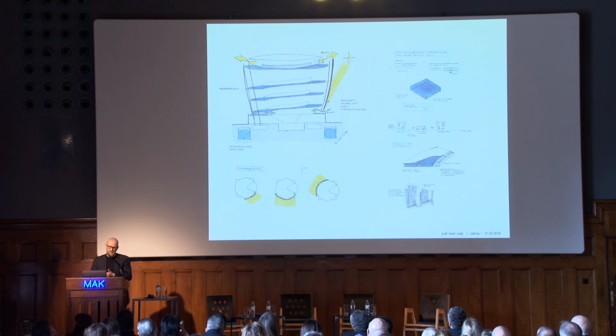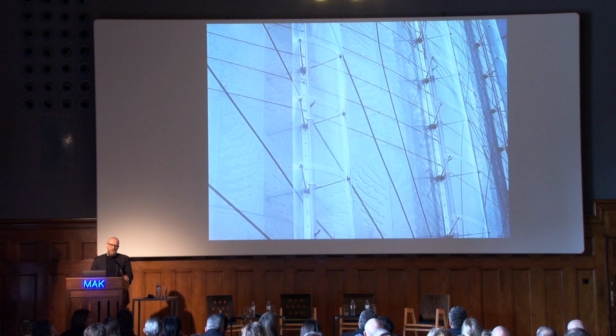The next thing, of course, is that this mass has to be regenerated: the energy has to be taken out so it can provide cooling for the next day. This occurs, as I said, by perspiration. So basically the building sweats. At nighttime, we spray the water into the atmosphere, it cools by evaporation, we collect it at the bottom of the building, and the cooling energy is ready for the next day.